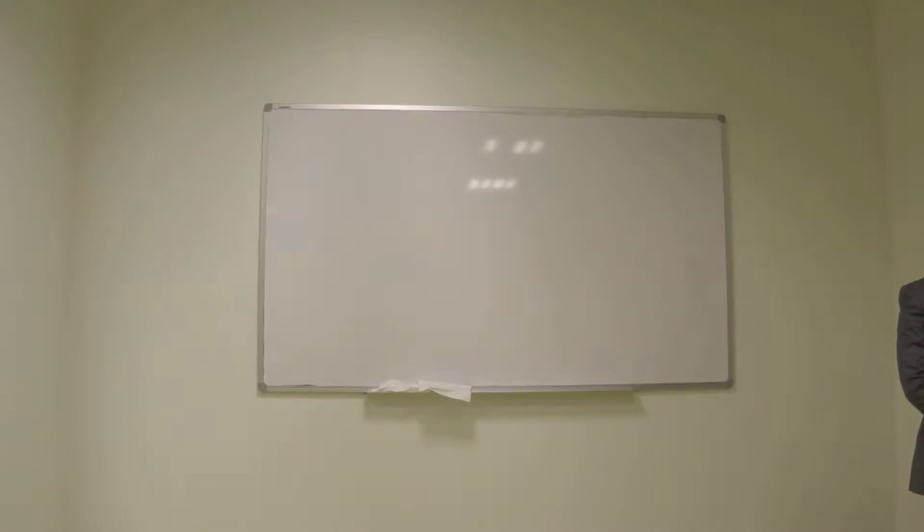For example, here I will give you one answer which will help you for solving the questions. If you are solving a truss having bigger forces, like 100 kilonewton, 200 kilonewton, and your answer is like 0.1 or 0.5, even up to 0.9, I think you can consider that member as a zero force member. But if your forces are very small, like 1 kilonewton, 0.5 kilonewton, or even 2 kilonewton, and you are getting answers like 0.1 or 0.5, then I think it should not be considered as a zero force member. Okay?